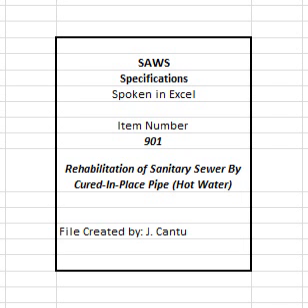The contractor shall also provide the following. B. Written notice to be delivered to each home or business 2 business days prior to the beginning of work being conducted on the section, and a local telephone number of the contractor they can call to discuss the project or any problems which could arise. C. Personal contact with any home or business which cannot be reconnected within the time stated in the written notice. D. Inform SAWS inspection department 48 hours prior to starting the work.